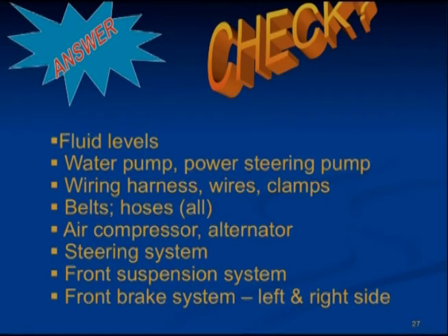Front brake systems, your air hose, brake chamber, slack adjuster, and brake rod, and also your brake drums. Check those for cracks, dents, or holes, missing or loose bolts. And your brake linings, where visible, should not be worn dangerously thin. Check the right side suspension system and the brake systems, just as you did on the left.